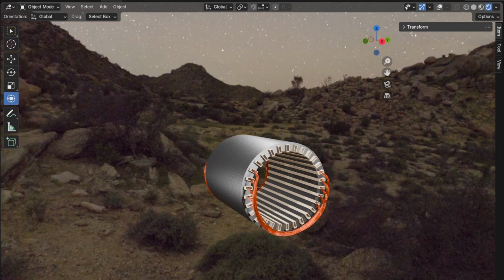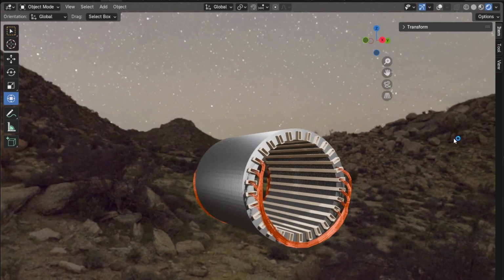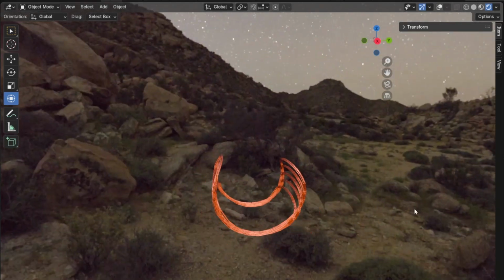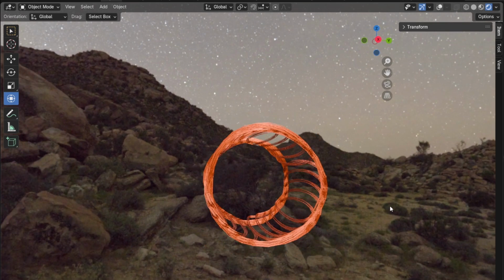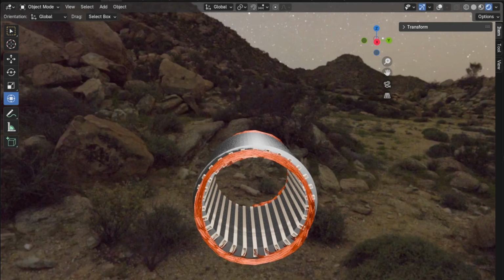And so here, I'll show you this. So that's what a single winding looks like. So you've got a winding pitch of 15. So this coil goes from this to here, and then that winding goes from there to there. But they're all together in parallel with one another, and they're on the same phase. So if we take the core and the liners out, this is what that individual winding would look like, and then all three of them together work in conjunction to create a rotating magnetic field. And I'll show you that here in a second. But let's talk about the rotor next.